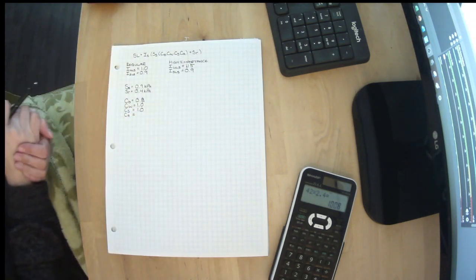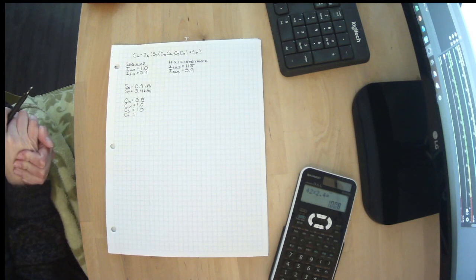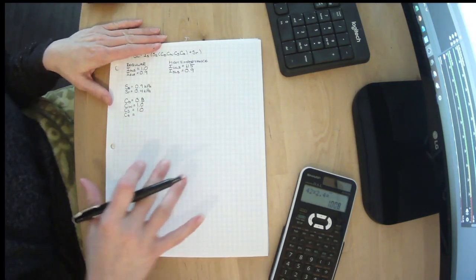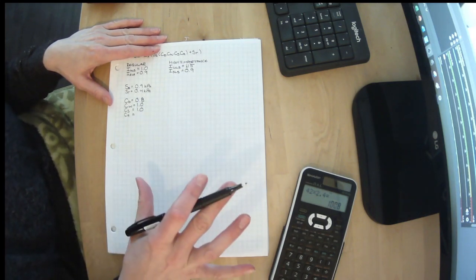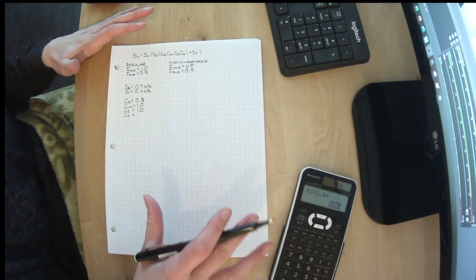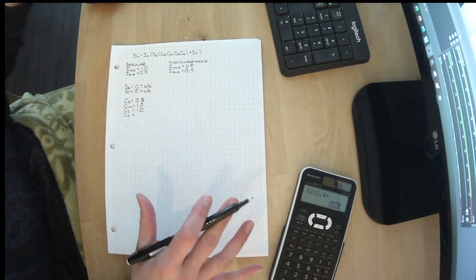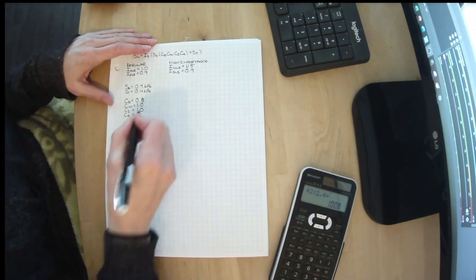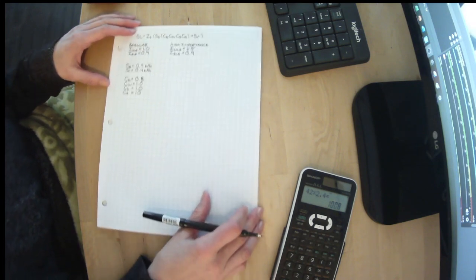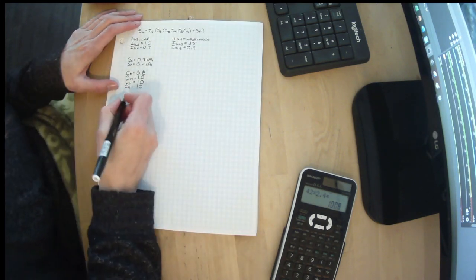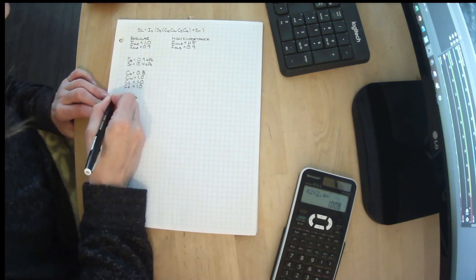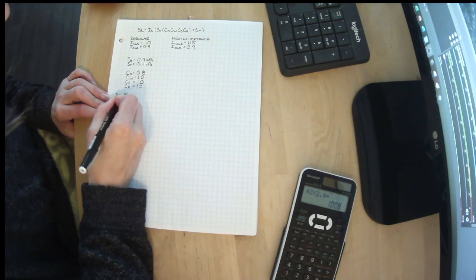And then our snow accumulation factor, or our CA factor, we know is very, very important, but what we're talking about is the overall building here, and I've told you you don't have to calculate it. It seems crazy that there'd be no mechanical units on this building's roof, but we're going with that. They have them protected in the basement, let's say. So we're going to use an accumulation factor of 1. So it looks like we can calculate our snow load for ULS. Let's talk about our regular importance here.